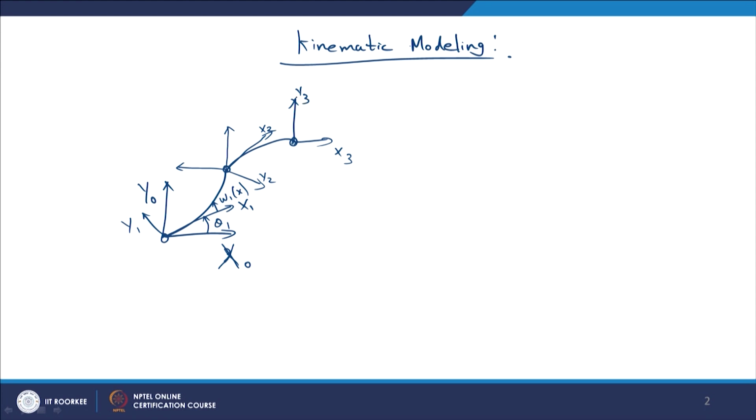The frames are finished now. So let me define this as the angle theta 2, and say this point, for example, this is the vector which is given by w2 of x2. So now we have the frames associated with the schematic of a two-link planar flexible manipulator. First we have the frame x0, y0, which is the base frame for the system.